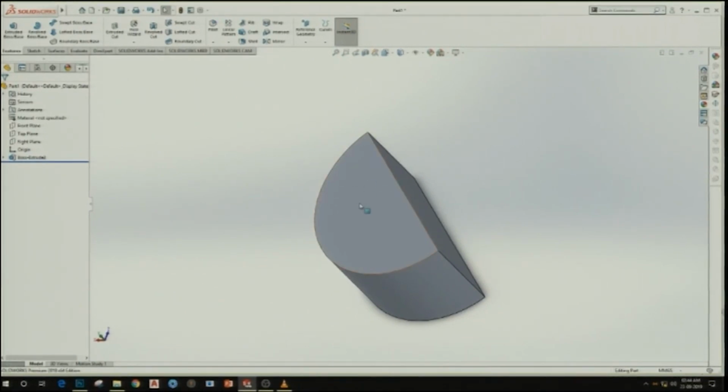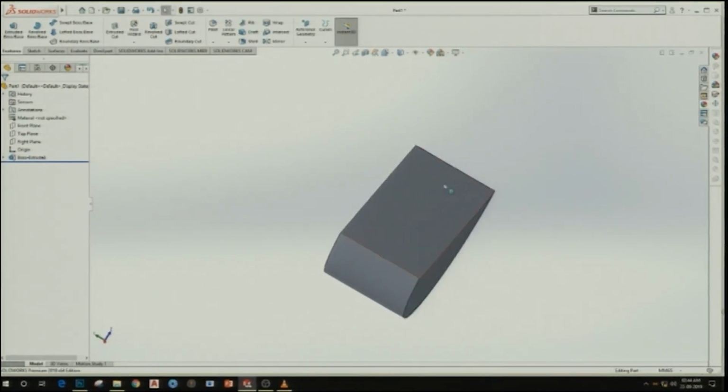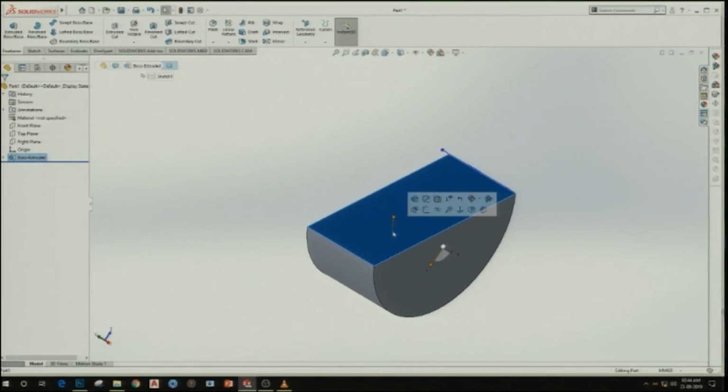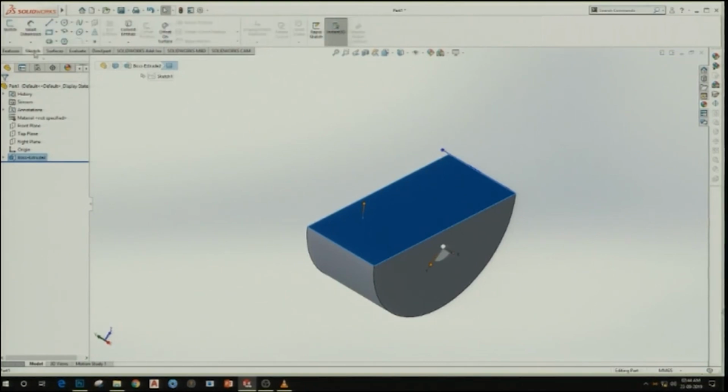Suppose I would like to create two circles over a specific face of this body. So, let me select this face here. Whenever we need to create something, we need a plane. So, let me select this plane. I will click anywhere at this point, and now this will be selected as my point, and I go to sketch.